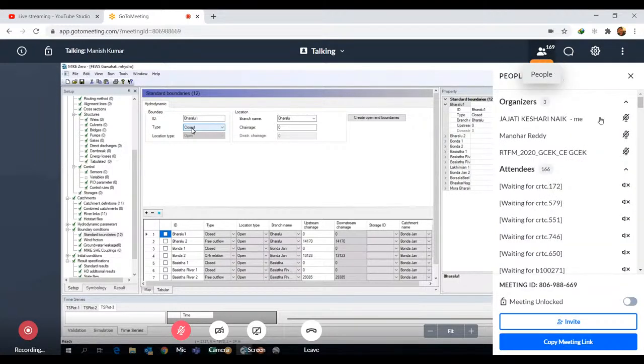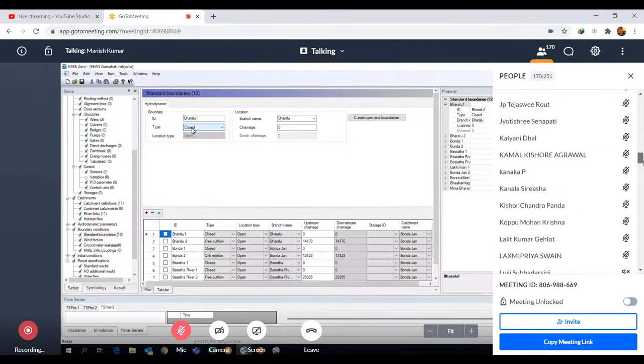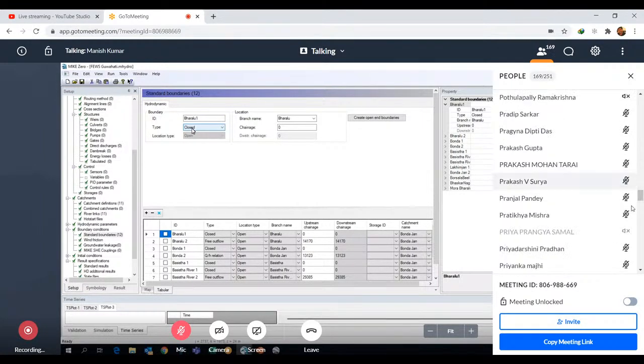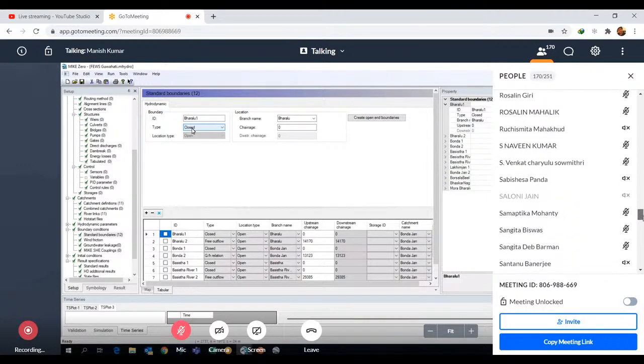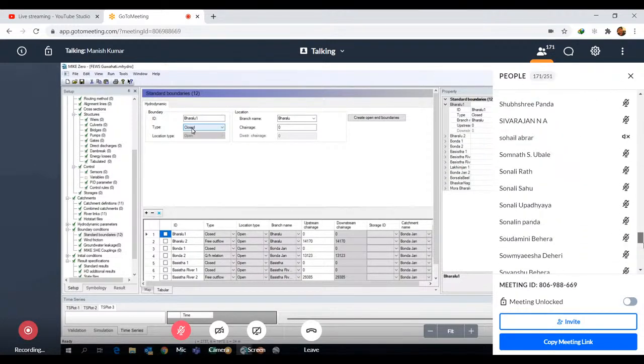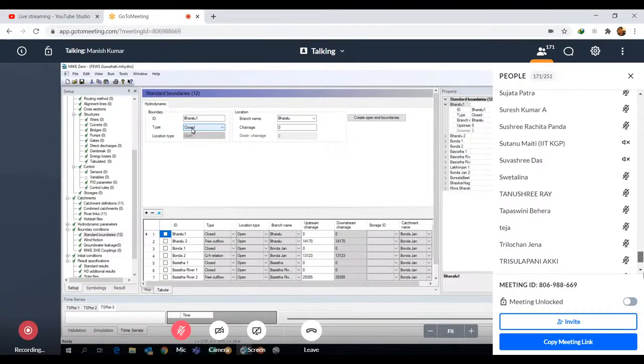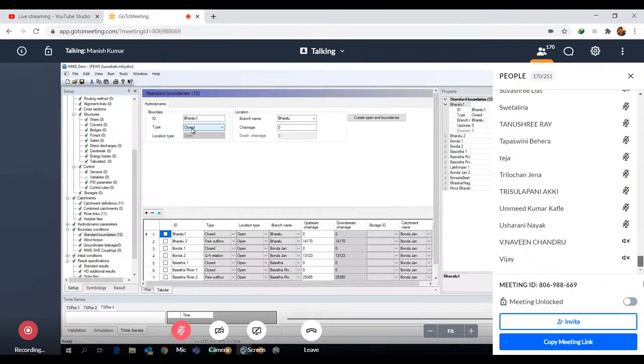Number one, if it's entering the sea, you can give a constant level, because discharge from a river will not change the ocean level. You can give a free outflow. You can give a QH relation. So if your end point is important for your modeling component, then you give a QH relation at the end point.